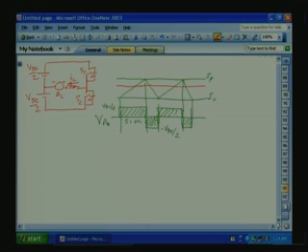Now, let us see for a hysteresis band IP and IV, what is the turn on and turn off period. If you know the turn on and turn off period, we can find out the switching frequency. The period is T on plus T off, that is one period, this is the T period. So T is known, we can find out the switching frequency.